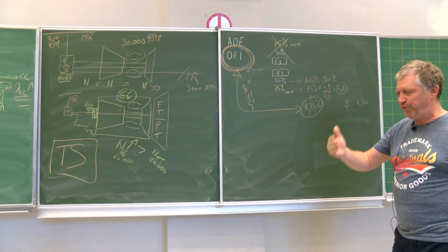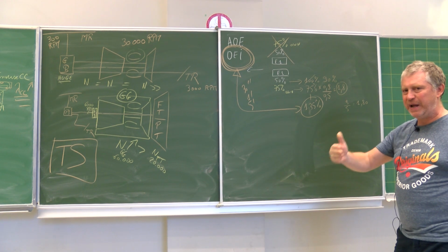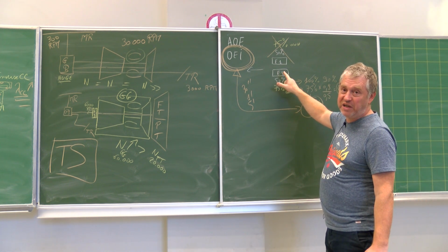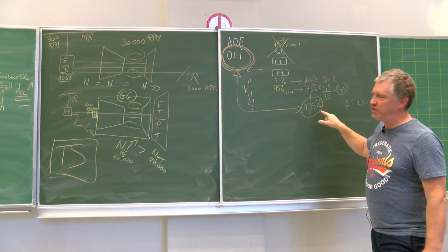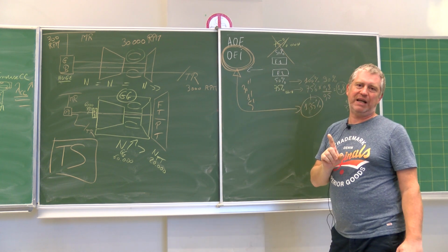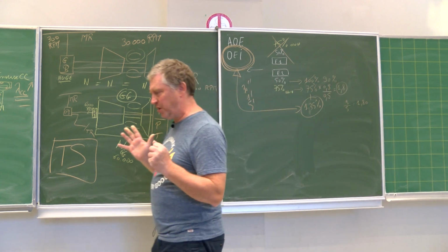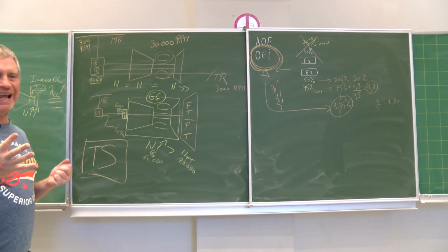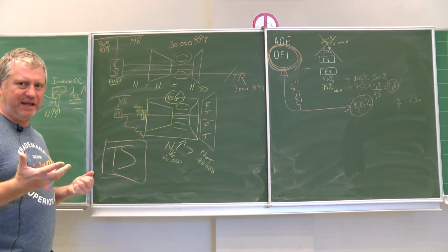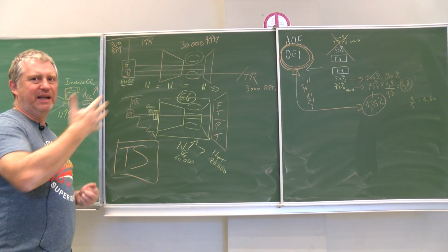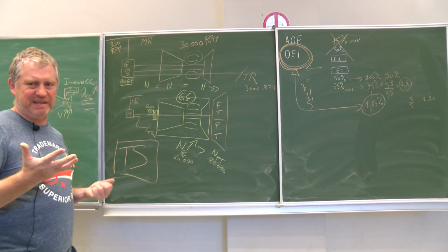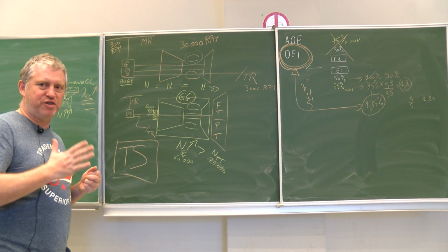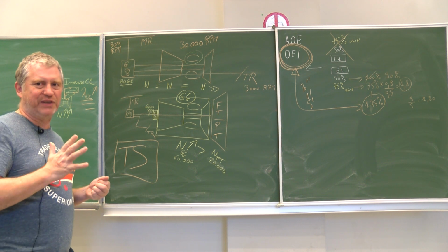helicopter will prove that the engine can be operated in this way, and the helicopter can also be operated with only one of the two engines operating in these conditions during a limited amount of time. And this is very special for helicopter engines. This is what is called one engine inoperative rating, so a much higher rating than the nominal one, than the maximum one when all engines are operating, but used during a very short amount of time.